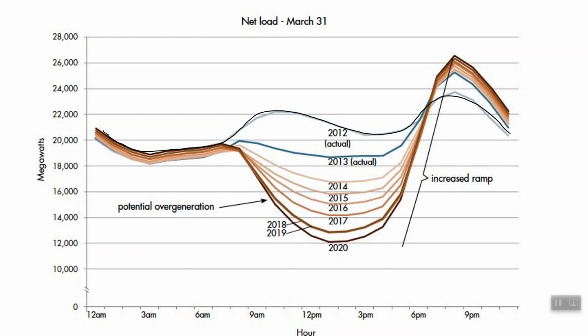And then as we increase the penetration of renewables, so with each year we increase the renewable mix, how many renewables we have in our total generation ability, and since our solar is going to peak in its generation at about noon or a little after, then the total amount of power that we have to generate is dropping significantly.